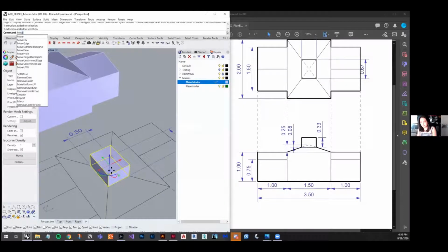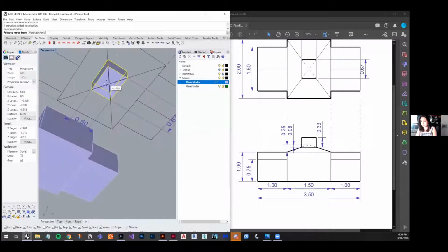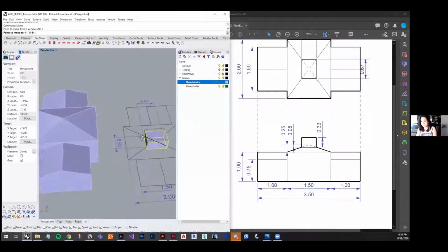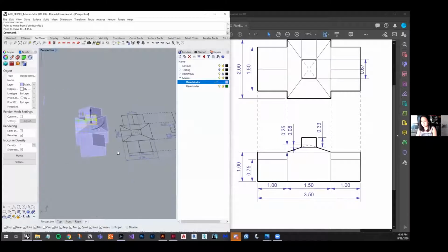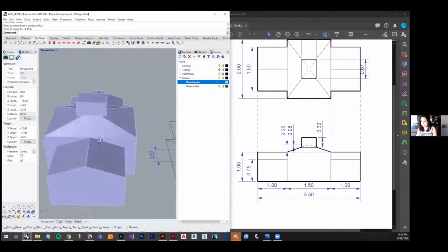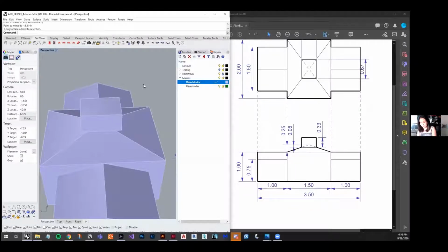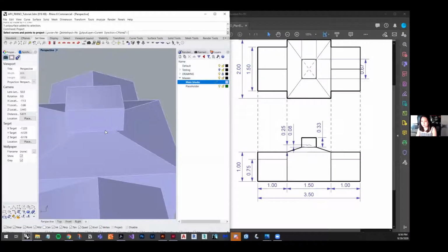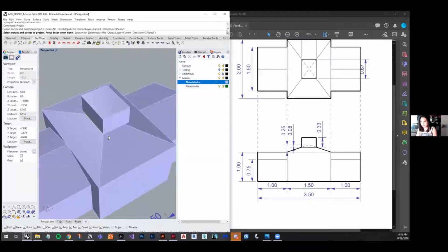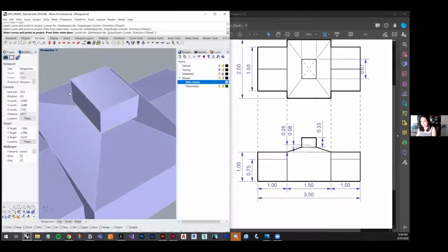First, we're going to move this over here. Let's just get it where it's the center, the center bottom, and we're going to move it to the top. Now, what I like to do, just to make it even more exact, is a command called Project. This is where we select the curves that we want to project. Since I'm just going to project it on these, just to show this corner and those two edges.